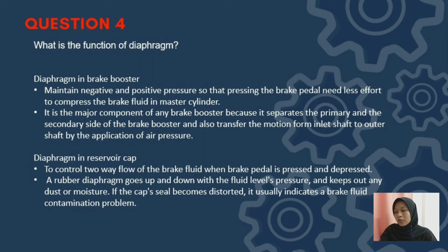Its function is to maintain negative and positive pressure so that the brake pedal needs less effort to compress the brake fluid in the master cylinder. It is the major component of any brake booster because it separates the primary and the secondary side of the brake booster, and also transfers the motion from the inlet shaft to the outer shaft by the application of air pressure.